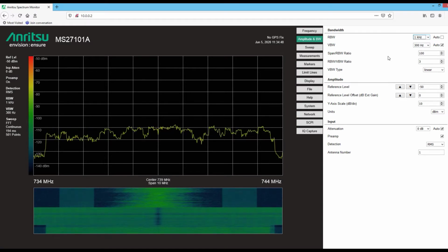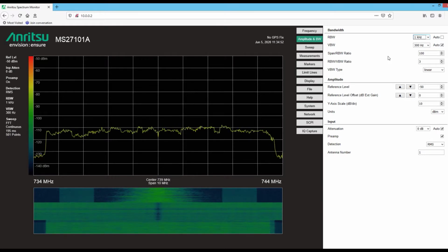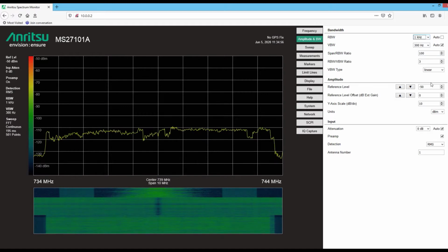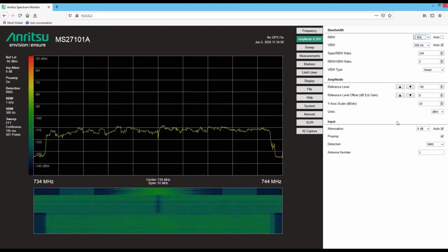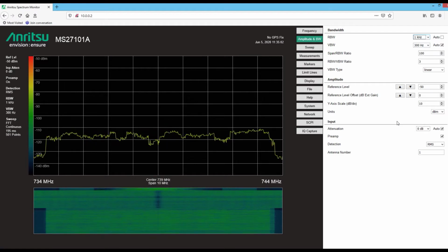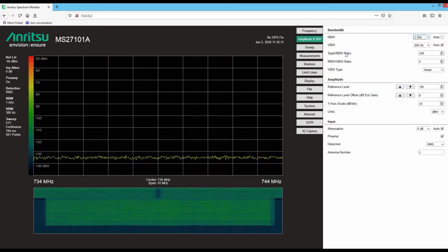So I have to remember for the bigger ones, I need a 1K RBW. And it will ask. Still with the negative 50, still with the auto. And just so you see it without a signal there, because that is an actual LTE signal that I'm picking up. It's negative 135. And that's very good as well.